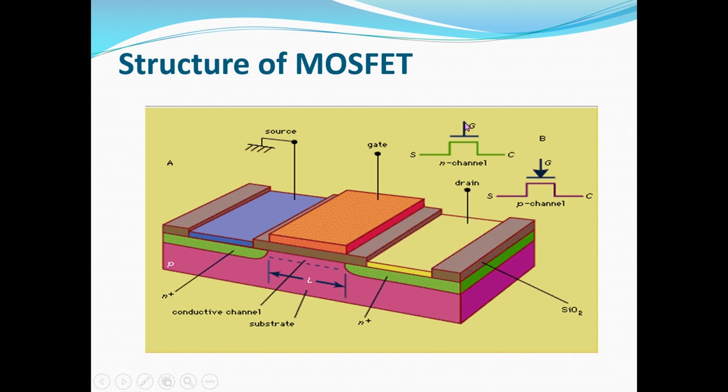So here there's a gate terminal where the input signal has been triggered into the transistor as an input. There are gate, source, and drain terminals, and this part is a SiO2 layer upon which the gate terminal has been laid. This is the place where the N type diffusions are being laid in order to form the source terminal. And the top part upon this N type source is the metallization part, and here N type impurities are being laid in order to form the drain terminal.